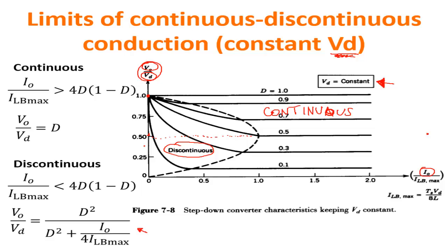In typical power management ICs, you have several DC-DC regulators, and sometimes you have several off-chip inductors around the chip, because every DC-DC converter needs one inductor.